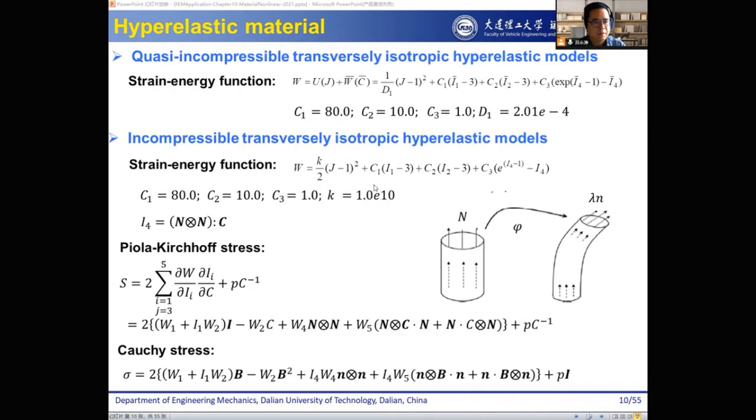Okay, so this is the hyperelastic material. It's a kind of nonlinear material, and whenever you want to simulate hyperelastic materials, for example rubber, in the FE code or FE software, you usually have to give values like C1, C2, and K, or here the fiber orientation N. So don't be confused about why you have to give those.